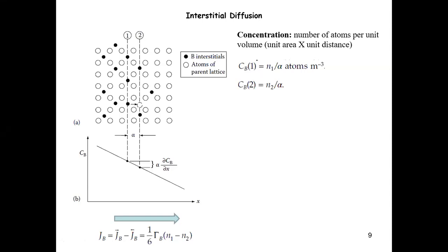So now what you need to do is just to divide this N1, which is already a density but an area density, by a distance, by a small distance, and convert this to a density with respect to the volume. And that is what we typically call concentration. Now, the distance that you divide this by is the separation distance between two successive atomic planes for these interstitials. This particular choice of distance is a little bit arbitrary. For example, you can also choose half of this,